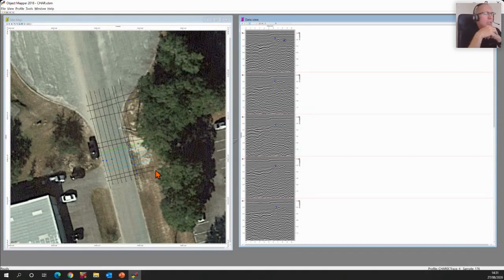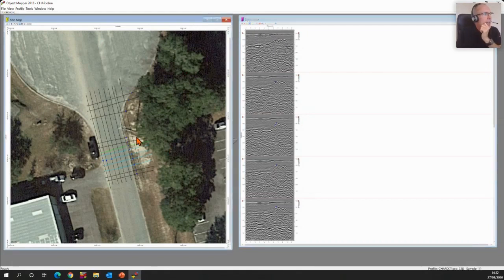If you go into the options tab, and then go into the marker options within the sub tab, you can actually give these a physical name, whatever you want to call the markers themselves.